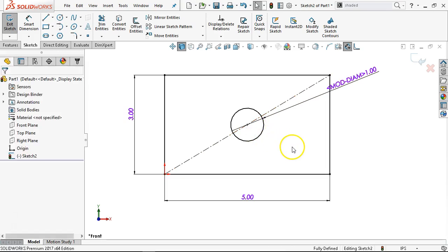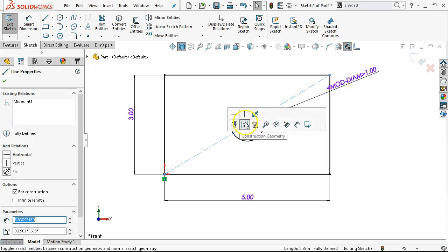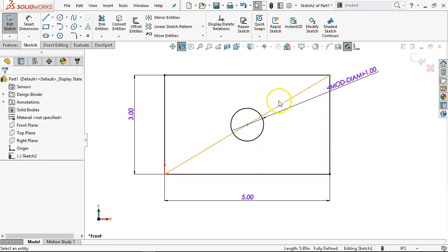and that is going to define my sketch. So I mentioned the center line. If I click on the center line and I tell it I want it to toggle construction geometry, now I've created 1, 2, 3, 4 regions. I can leave this, but now I have to make additional selections when I create the extrusion.